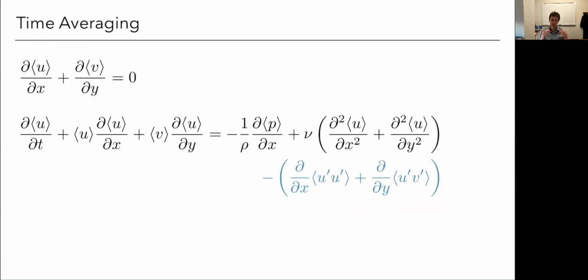It's not necessarily purely physics-based anymore, because there's not a pure physics model for it. I'm going to use physics to maybe try to motivate a model, but I don't have a model. I have to invent one. And so there are many turbulence models that exist. These things here, if I was to write it in a general way, U_i' U_j', where these are the fluctuating components, we call these Reynolds stresses. And this, written in this form, we call the Reynolds stress tensor.